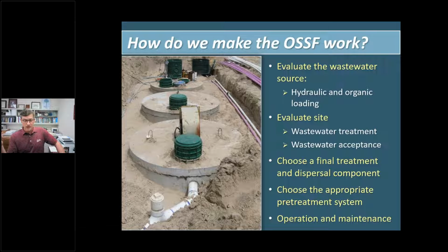When we think about home septic, on-site wastewater, human waste and toilet paper need to be the only things going into the tank. Anything else that we may put in there can potentially have a negative impact on the system, and we just don't want that.